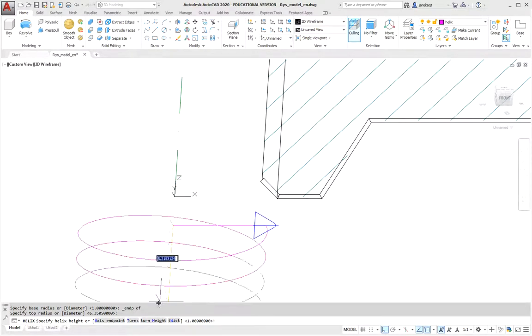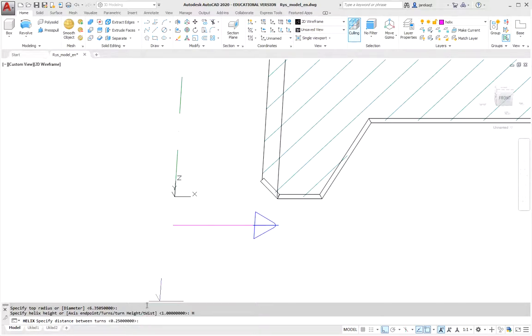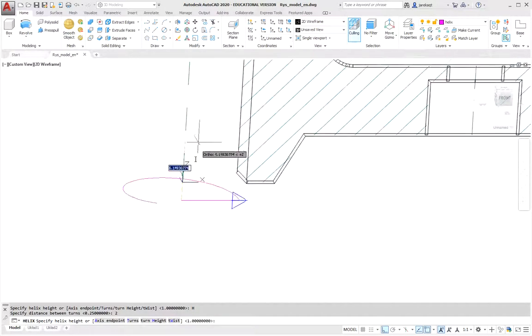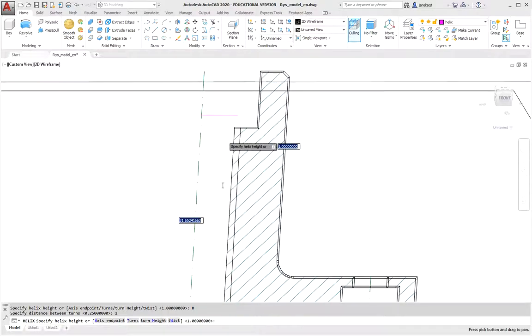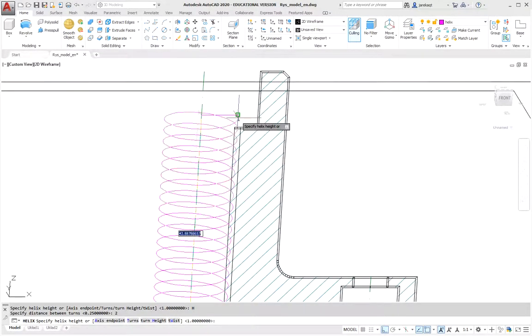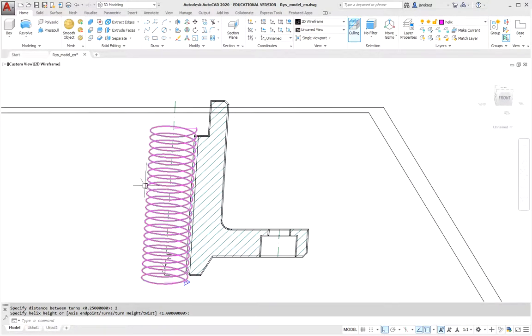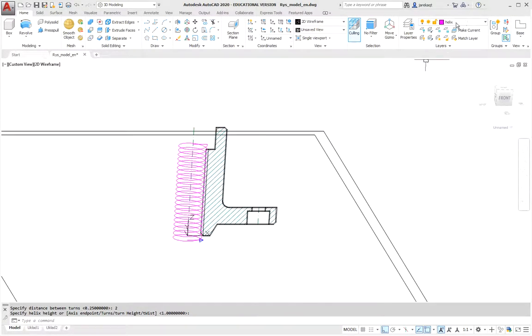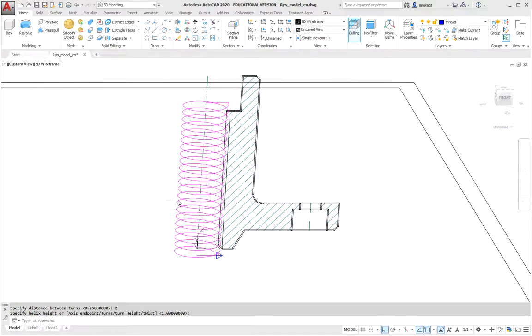We will set the jump again after 2. We will say that the end of this helix is the A to B. In this place where we indicated an even number of jumps, the helix ends. Now we have the line ready to create the thread, so now let's create this thread. We will drag the prepared triangle along the helix line.